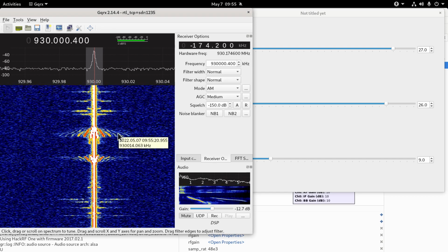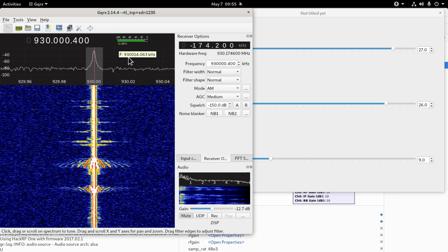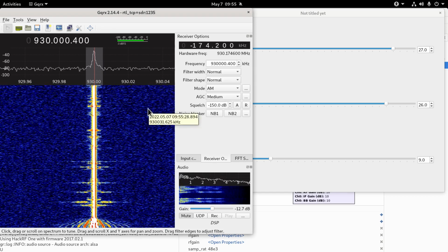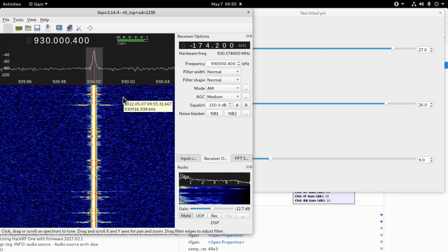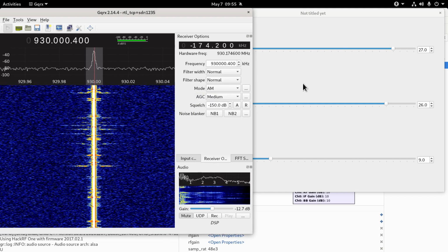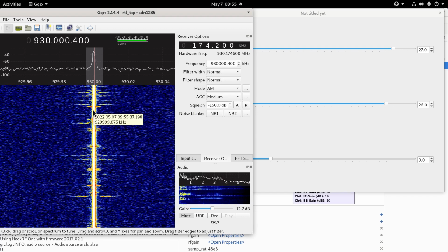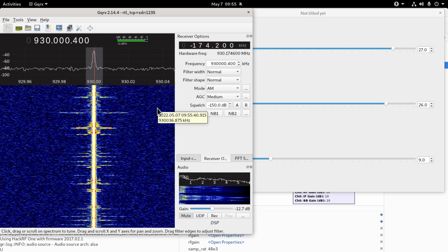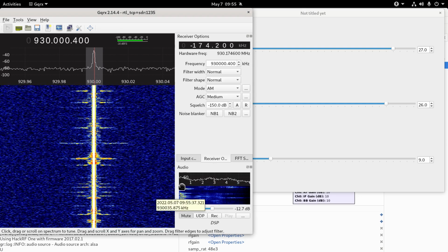Okay, so what you can work out by that is the bandwidth that this whole thing's going to take will be 2 times the maximum frequency that's being modulated. So let's say I put a filter in here and make it so you only use like 5 or 6 kilohertz. That'll be like 10 or 12 kilohertz bandwidth for the whole thing. So that's an AM transmitter right there.